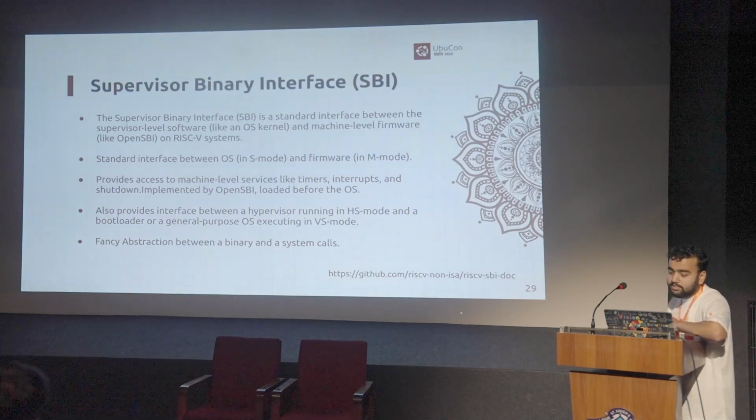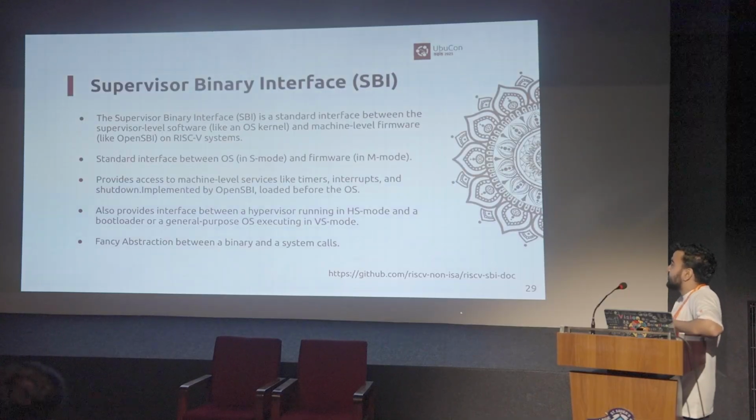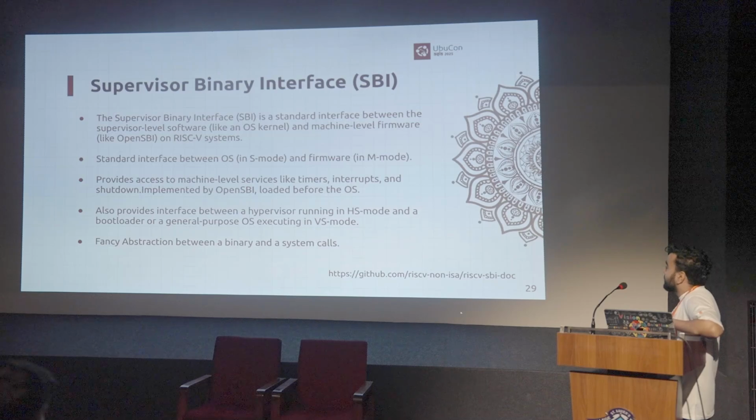And then the supervisor binary interface, the SBI we have just discussed. It's a standard interface between the OS in S mode and firmware in M mode. So this is not the common flow that we see in our day-to-day devices. It's responsible for providing access to machine level services like timer, interrupts, and shutdowns. It's a fancy abstraction between binary and system call.